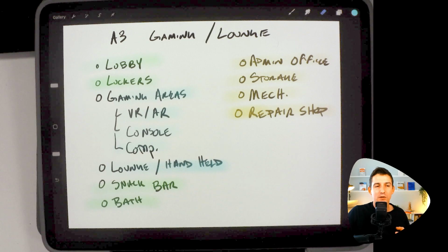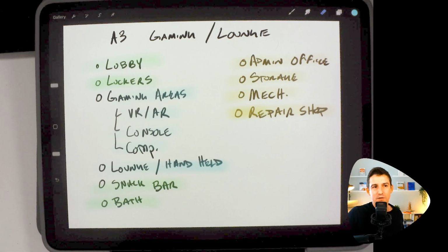The other thing I need to keep in mind is I still need circulation. I need to think about egress. I need to think about accessibility, but we can infuse that into our design a little bit later. So if it's going to be multiple stories tall, I need to be thinking about two ways, two staircases to get out. And you can look at code based on building classification to find out how many of those need to be fully enclosed and protected with 2-hour ratings, how many can be like decorative staircases.